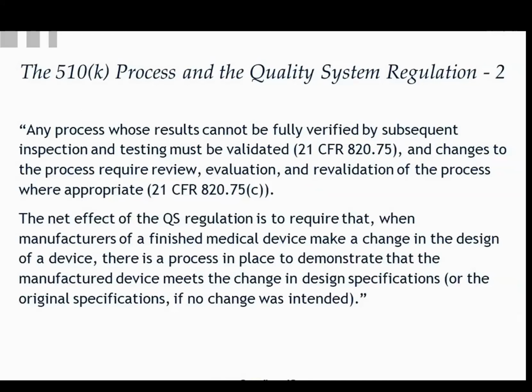So wherever there is a question, go ahead and do that additional validation downstream where you feel you've addressed it upstream. Especially that's true if you're dealing with sample inspections with humans, as opposed to automated, 100% inspection with validated equipment.